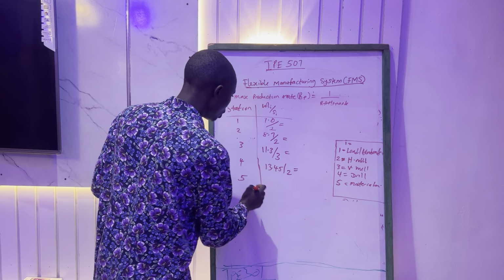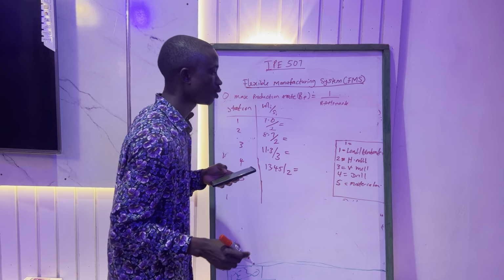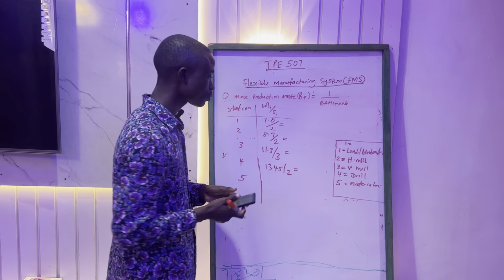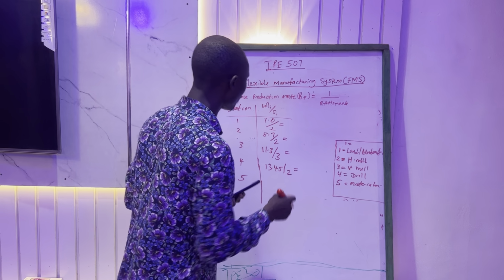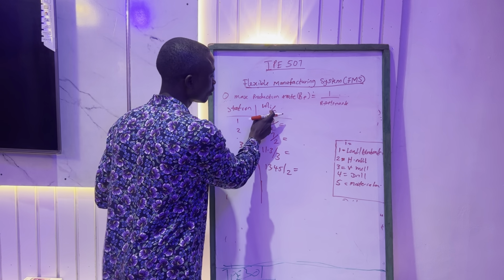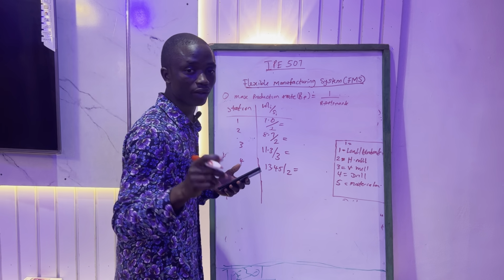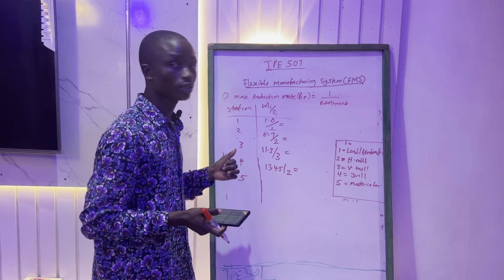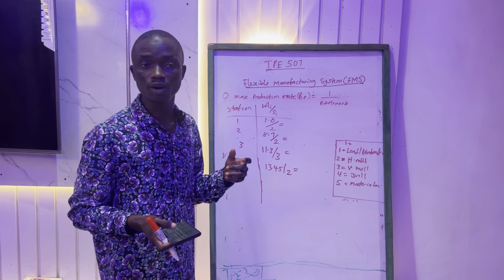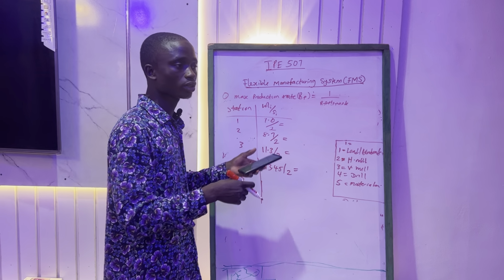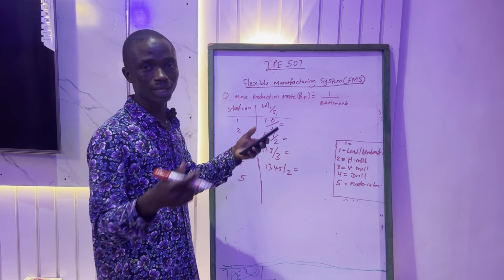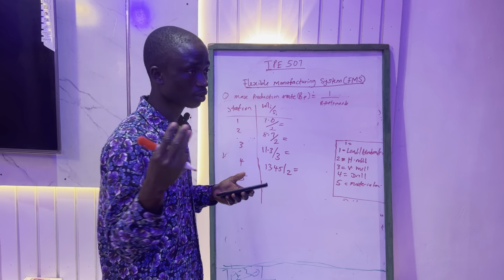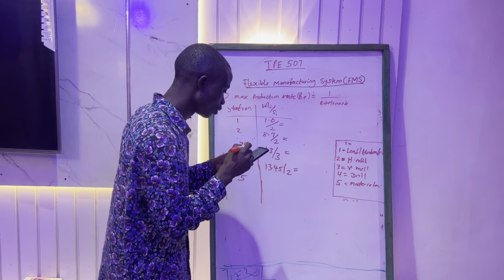Now for the material handling system. For the material handling system, the formula for finding the WL/S is different: instead of the number of servers, we have the number of carriers. The number of carriers is what represents the servers there, like the robots and the conveyor belts. These are the carriers, and they are 3. That has been given in the question to be 3.